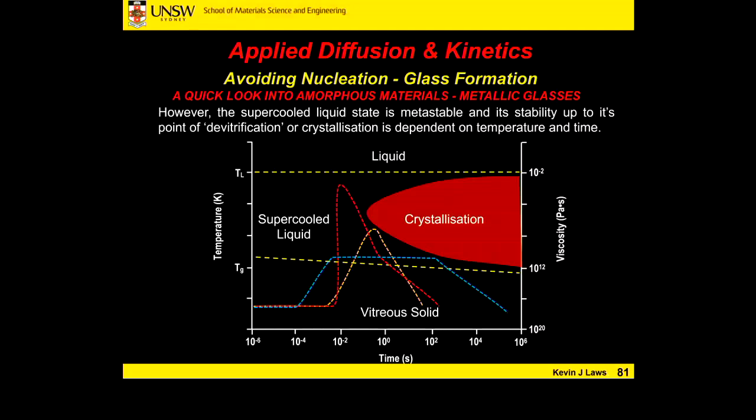And it's the same for pellets of polymers or glasses that we want to turn into something else. So what we do, we take that material, and now it's still on the same diagram wherever we finished up. Say this point here. To form it again, what we have to do is heat up and go above the glass transition temperature. This is where it transforms from this vitreous solid, something as hard as window glass, to a supercooled liquid, where it's as viscous as chewing gum. So that's what we're doing.